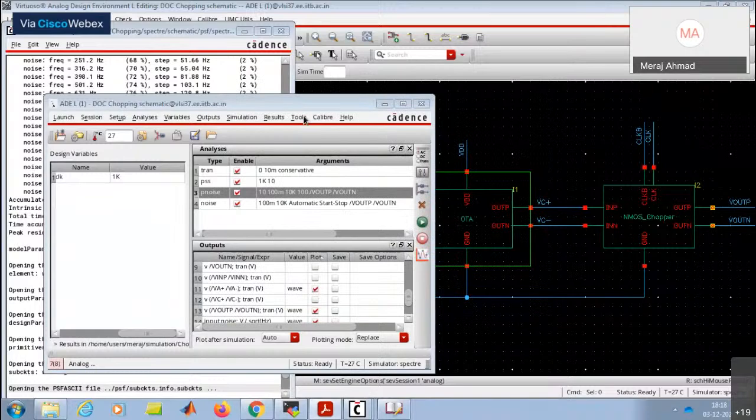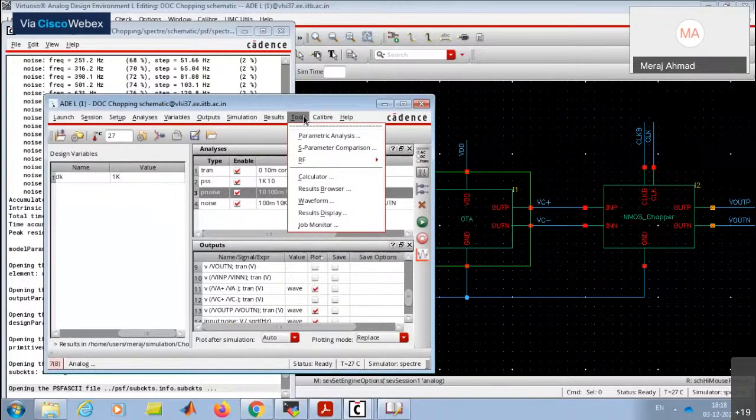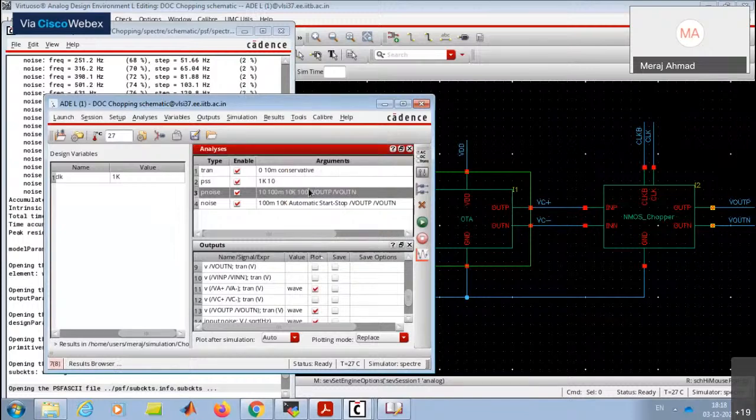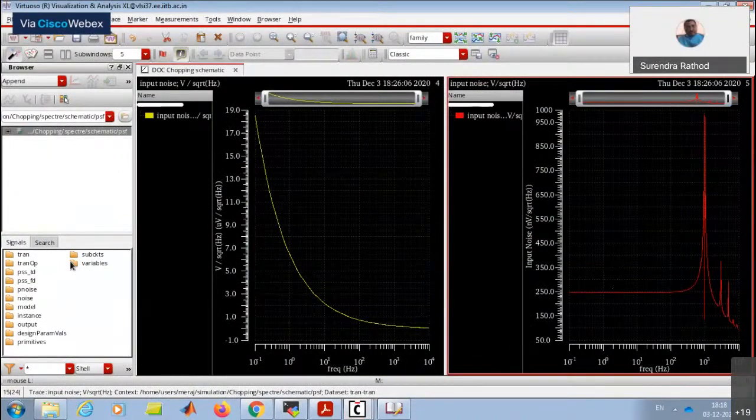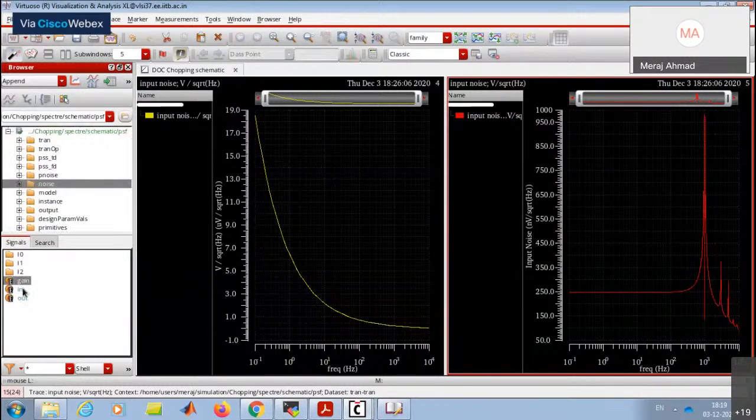Since we have time and we are not having any questions, there is one option called result browser for debugging circuits. This is really very helpful, which is in tools and result browser. Whatever analysis we do comes here. Now we have run pnoise, tran, PSS, so we can get all these parameters for individual components. What is the noise of each and every component?